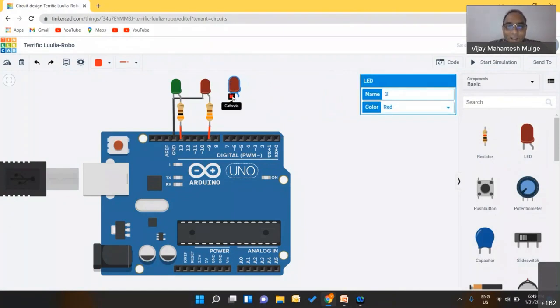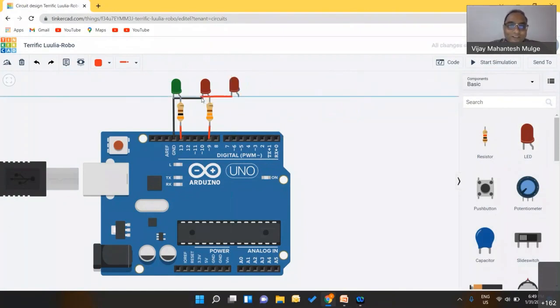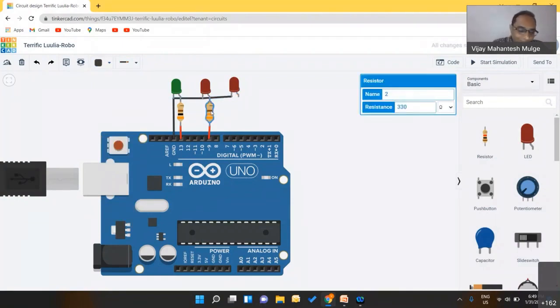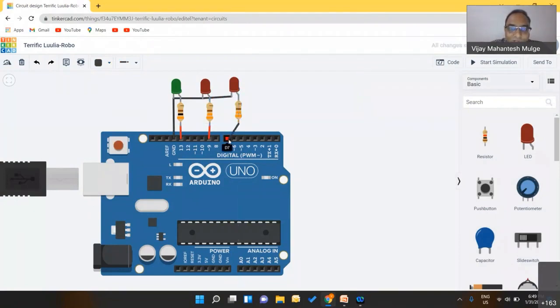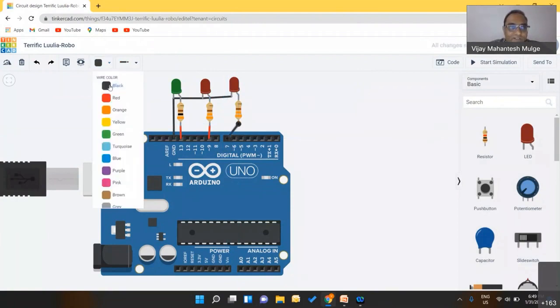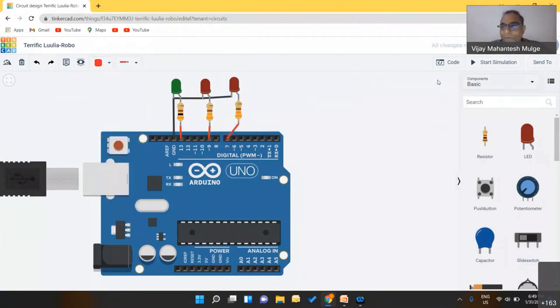So now if I can add one more, this is just for the sake of some learning here, right? I will pick up one more LED and then I short their ground. So I will connect this resistor here. You can connect it to any pins, right? So now if you do this, again, change the color, just indicating that it is power now.